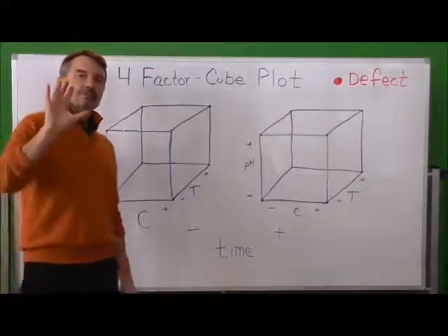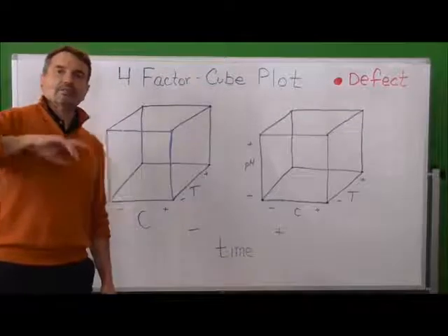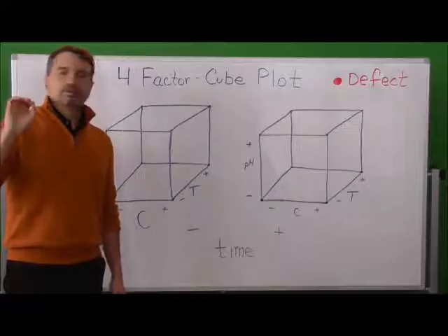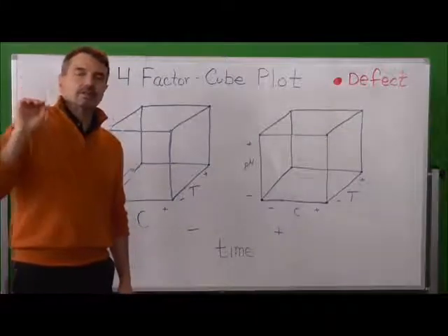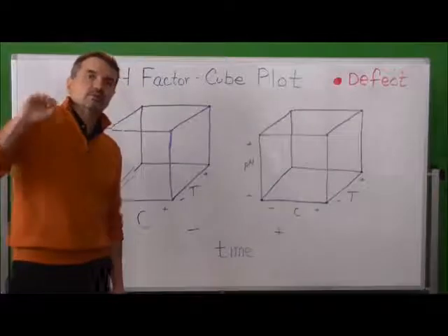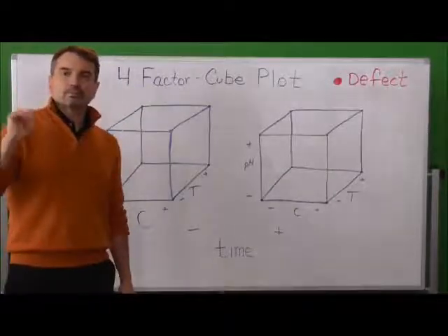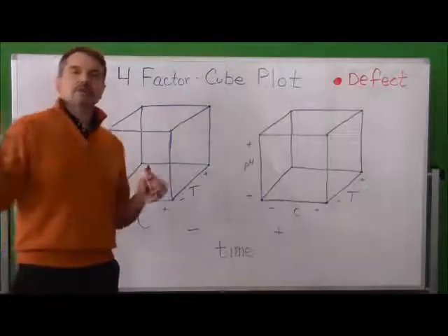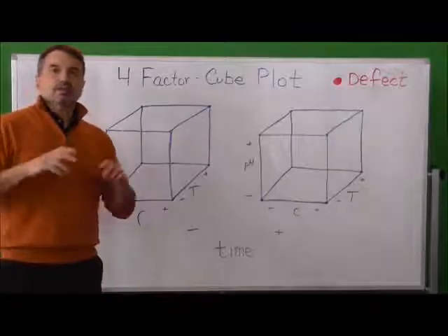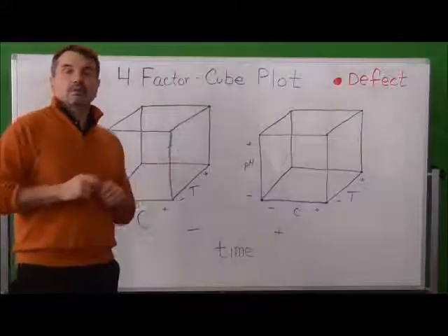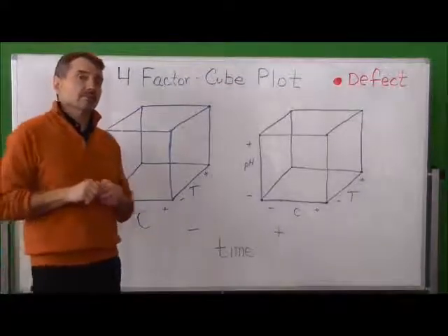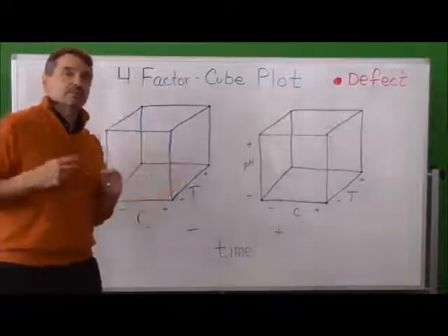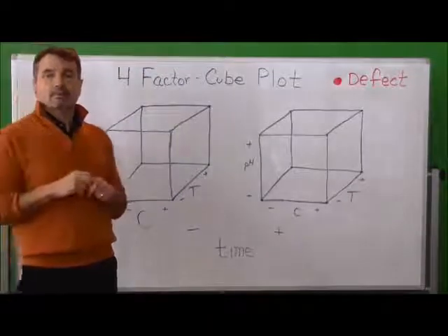Okay, now what we've done is we've run the 16 runs, and that may have taken 8 hours, that may have taken 12 hours to do this. I strongly recommend you not do it over multiple days, as you may have an environmental factor come into play, or other factors such as raw materials, changes in crews, and things like that occurring. With those changes in factors that sometimes you cannot avoid, the idea, as we showed on one of the prior videos, was to reduce the variation off the process, and to do that over as short a period as possible. So let's proceed as if we did these 16 runs over an 8-hour period, or a short period of time.